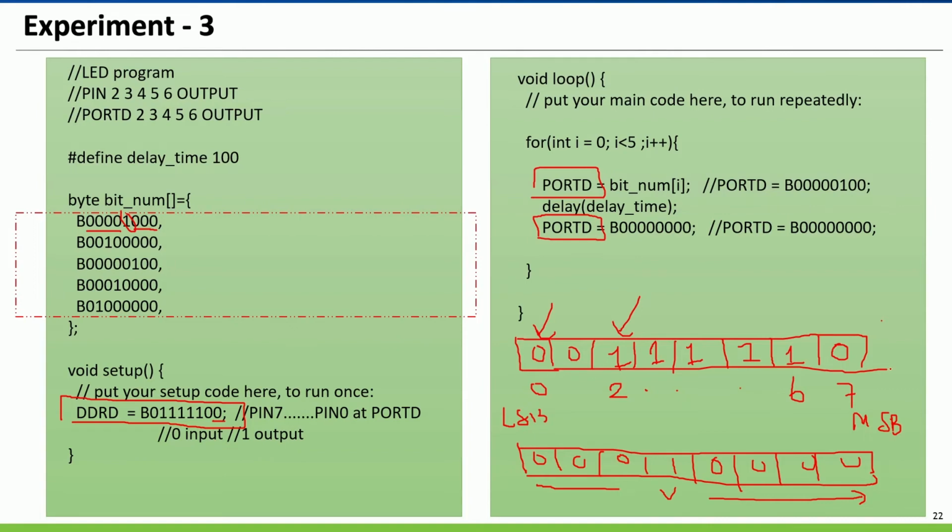You simply just put a digital pin for setting the register of the microcontroller using the function DDRD for setting input and output, and using PORTD you set high or low. Similar to digitalWrite. In this case, you use PORTD.